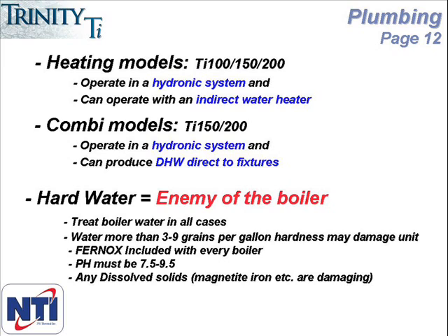So what we do at NTI is we include a bottle of inhibitor with every boiler, and we suggest treating the water in every installation, regardless of hardness level. In cases where the water is not excessively hard, there's really no downside in using the inhibitor. But in cases where the water is quite hard, the inhibitor will help prevent limestone and magnetite deposits.